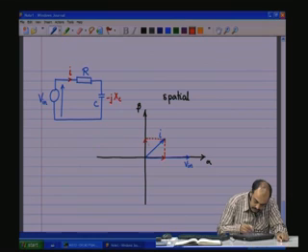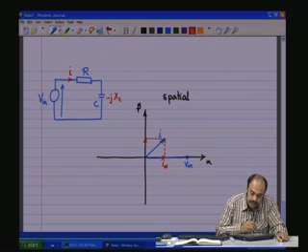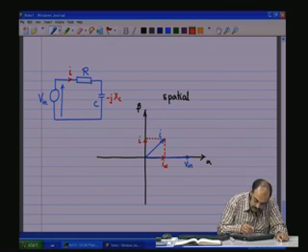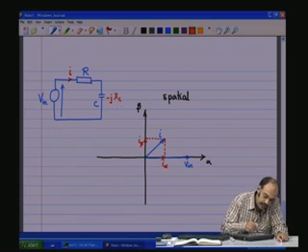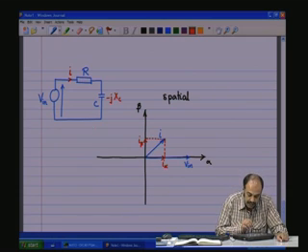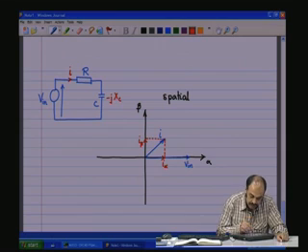which is in phase. We call that one I alpha, and there is another component which is 90 degrees phase shifted with respect to V in, and we call that one I beta. So, I alpha is the in phase component of V in, and I beta is the component of the current which is 90 degrees or orthogonal to V in. Now, this whole unit is rotating at frequency omega, and this is a picture at an instant of time when V in is equal to 0. That is, the V in projection is equal to 0 on the temporal axis.